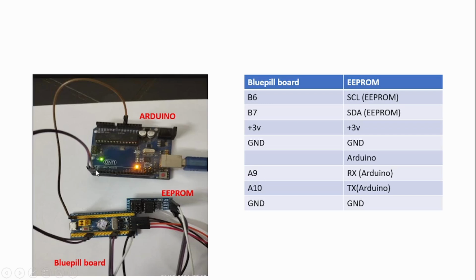And if it will be a permanent setup, then it is better to use direct soldering, right? But since this is for experiment purposes, I use jumper wires. Because of them I sometimes get garbage values, but after pressing all the wires properly, I get the message. So don't worry about that.